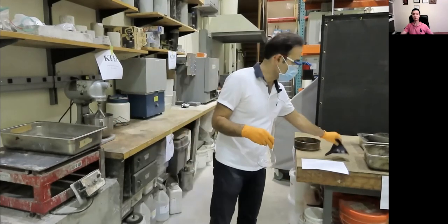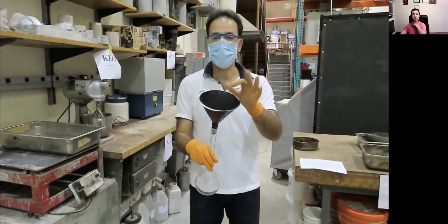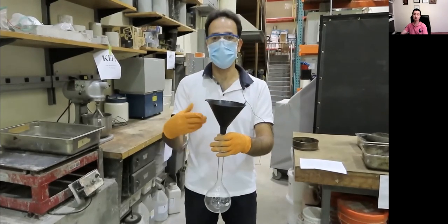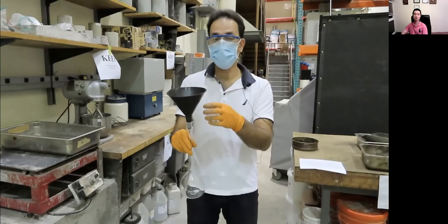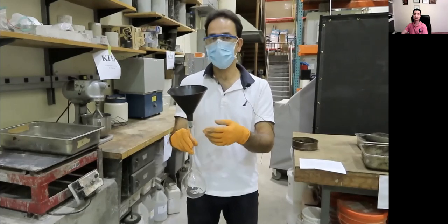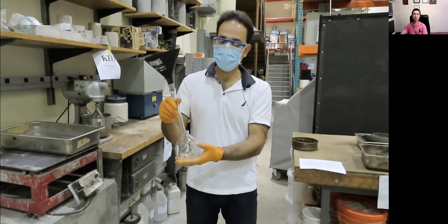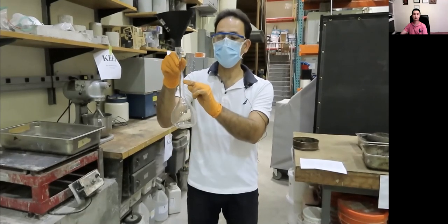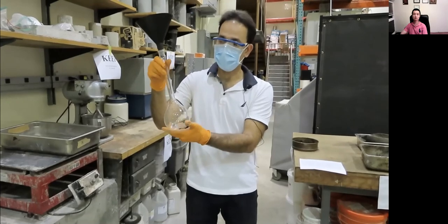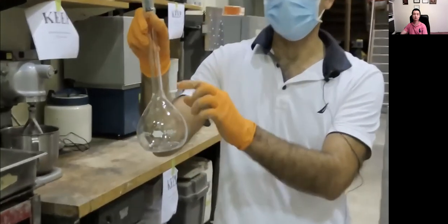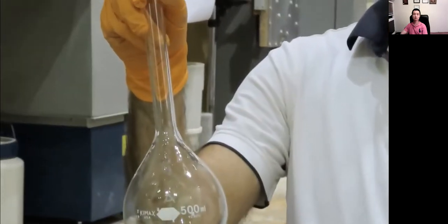I'm going to use this funnel. Hopefully my aggregate passes through this funnel. If not, I'm going to use a piece of paper to do it. Dump all the fine aggregate, 500 something grams of sample, into the pycnometer. There is a mark here that shows the capacity, the volume of the material inside the pycnometer, is right on 500